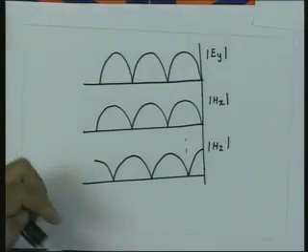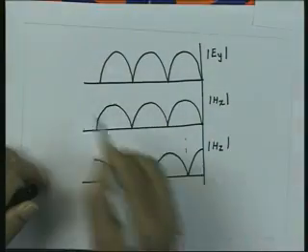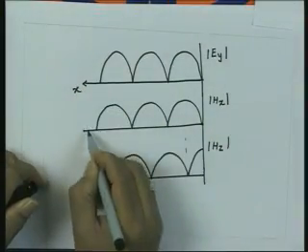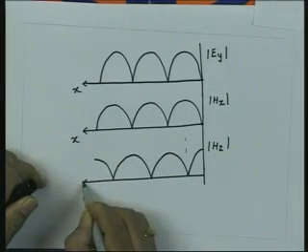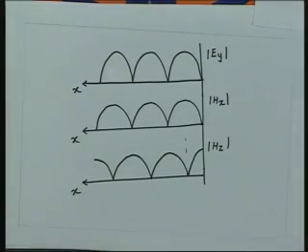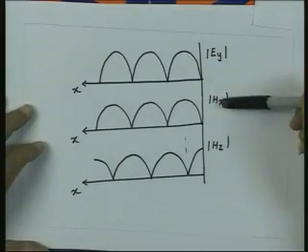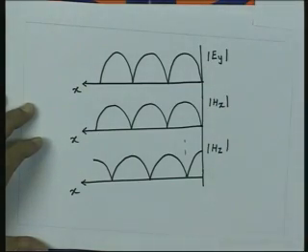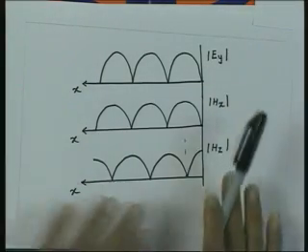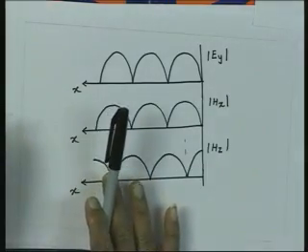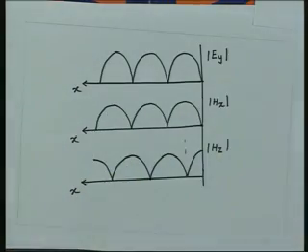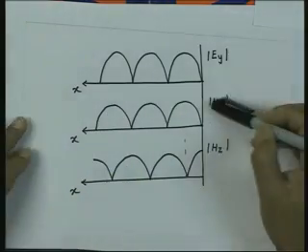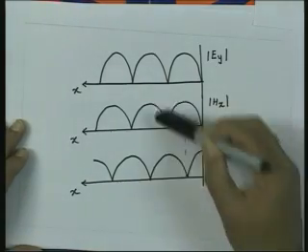So now we can make certain observations. This is the standing wave pattern created in the x direction. The Ey and Hx patterns are aligned in space, whereas the Hz pattern is shifted by a quarter cycle with respect to these two patterns. So wherever Hx is maximum, Hz is 0, and vice versa.